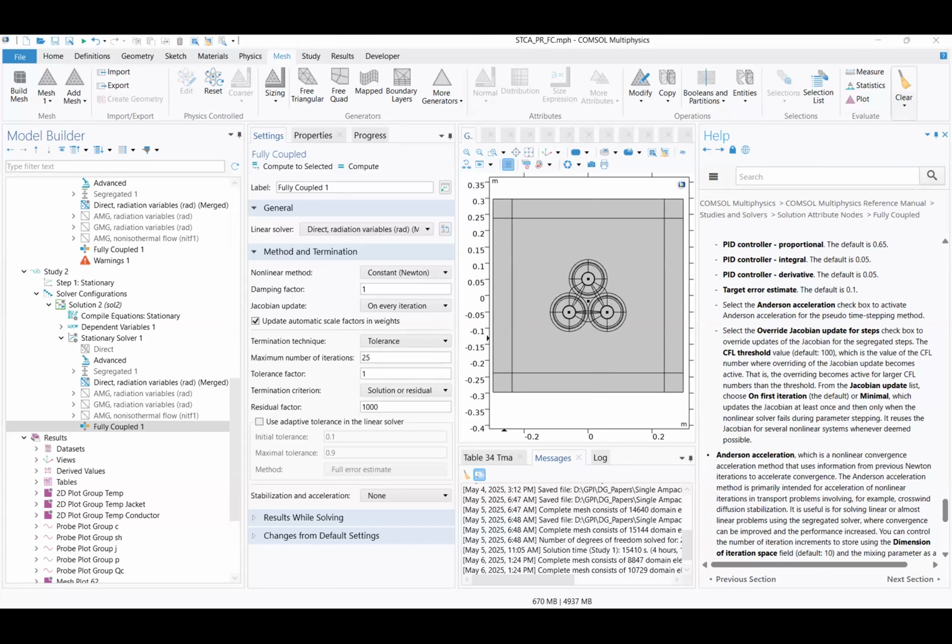Well, I think we can do it. I can only tell you what we are doing. The first thing that we are doing is in the elements, we are not using quadratic interpolation. They suggest to use linear. You remember that in this case we are working on the no load current, which is highly nonlinear because of the BH curve of the core. So we are using first linear interpolation, and you can change that in the physics.